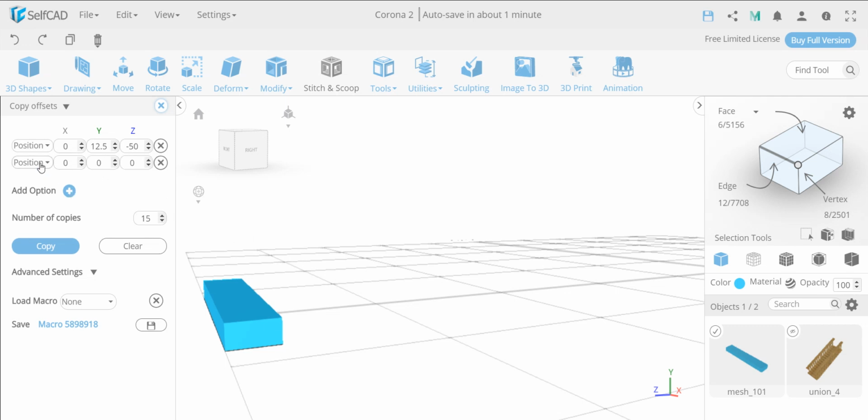I'm going to add another option now, which is size. The size, I'm going to scale it bigger by a delta of 25. Now, what's happening is because this is a symmetric scaling, when I'm making it bigger, it moves it up by 12.5 and it moves it down by 12.5. So if I want this to be aligned with the floor, we already have it down 12.5 from the size. So I only need to move it the remaining 12.5. That's why it's important to understand how this is working. Symmetric and it's delta based.